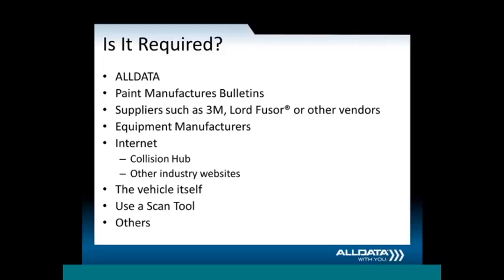Well, what Kristen and Doug Gans showed was that on this particular vehicle, which was a Mercedes, there was an airbag pressure sensor in the door, and we actually have to replace the door vapor barrier so that no air leaks in and causes an airbag fault code. So again, some great resources on the internet.